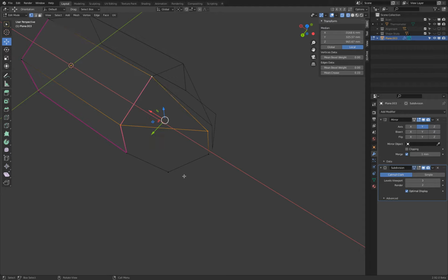This is a triangle, that's not good. And here, 1, 2, 3, 4, 5, that's not good. I want there to be 4, 4, and 4, which means this edge needs to have a subdivision. So we select the edge, right click, subdivide.